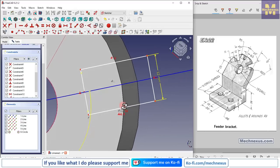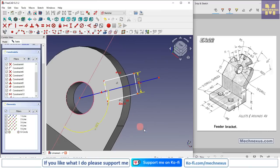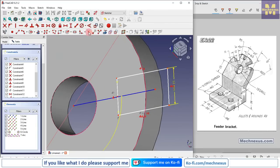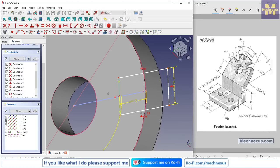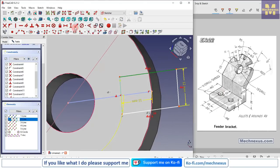and here we will trim the line. We will project the geometry and we will trim this construction line. Select trim and trim it so that we get a point. So we get a point and this line, select it and provide the dimension of 11 mm, and we will keep this value approximate.